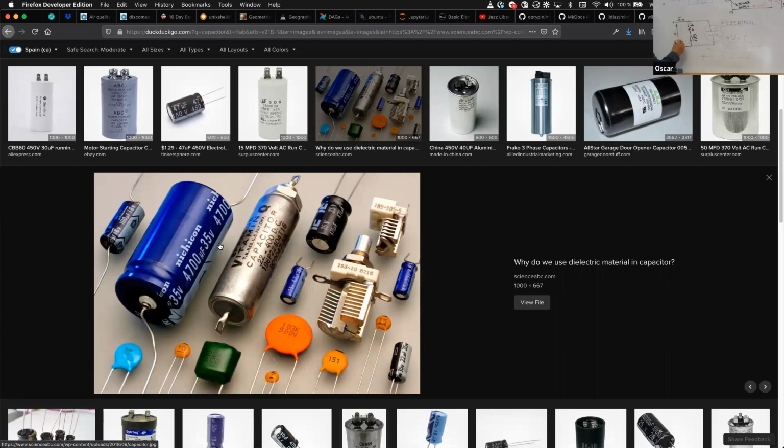So when you have power in here, there's voltage going in, the LED is shining, the capacitor is charging. If you remove this, the capacitor is charged, and then it will discharge through the LED. And the LED will make a nice fade out, powerful at first and then it dims. That happens many times with power supplies.